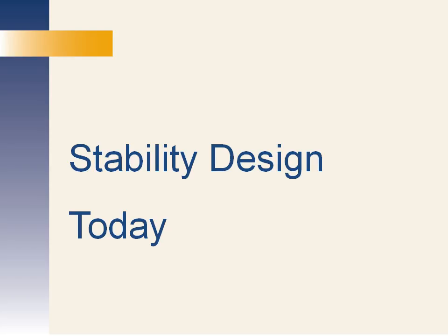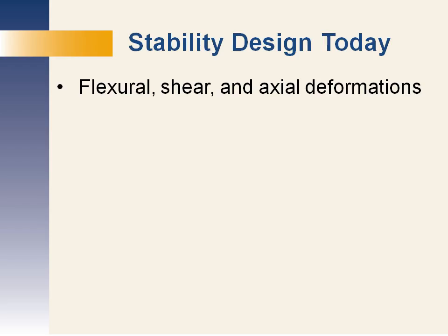We can find that in the 2005 and 2010 AISC specifications. Section C1.1 in either one of those documents says that any method that satisfies 5 needs can be used. And let's look at those 5 things. First thing it says is we have to consider flexural, shear, and axial deformations.